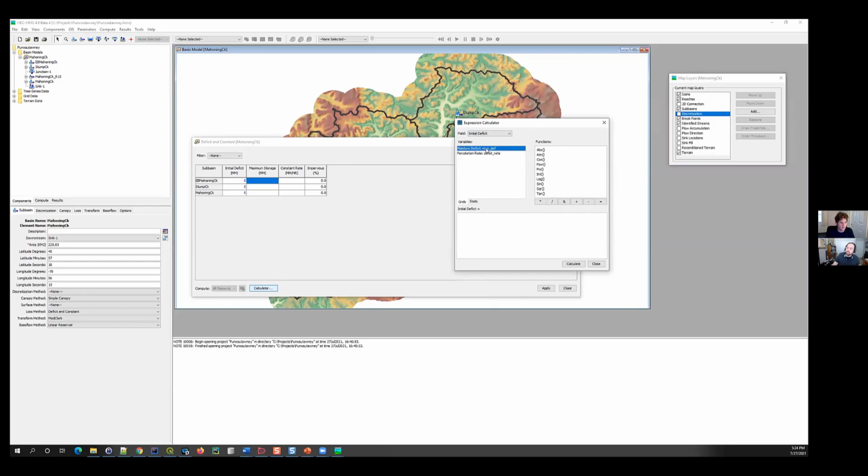So I've already loaded this raster into HEC-HMS. Now my maximum deficit values are in inches, so I'm going to multiply by 25.4 to get to millimeters. So you can see I've now done zonal statistics on that raster to come up with the maximum storage.